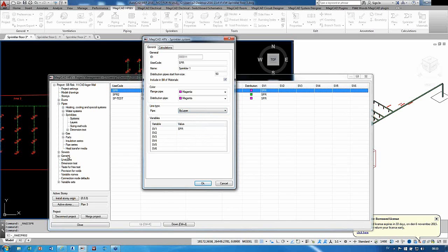I have my pipes so they change line type between heights. It's a setting that we have here up in the Nordics. If the pipe is below 0, it's dashed. If it's between 0 and about 1.5 meters, it's continuous. If it's between 1.5 meters and up to the roof or the slab, then it's dash dotted, and above the slab it's dash dot. So the contractor can see mainly where this pipe is going to be installed.